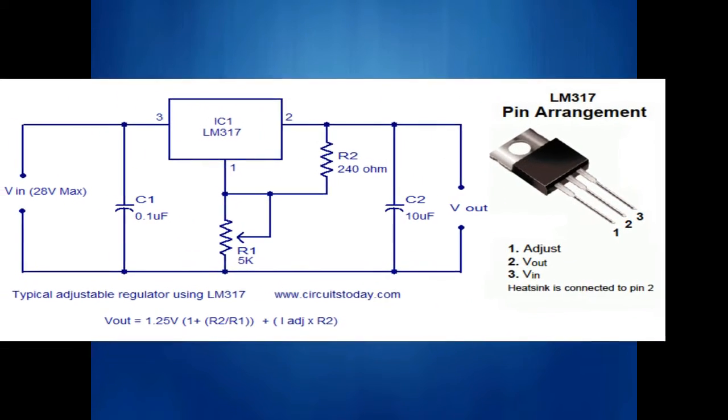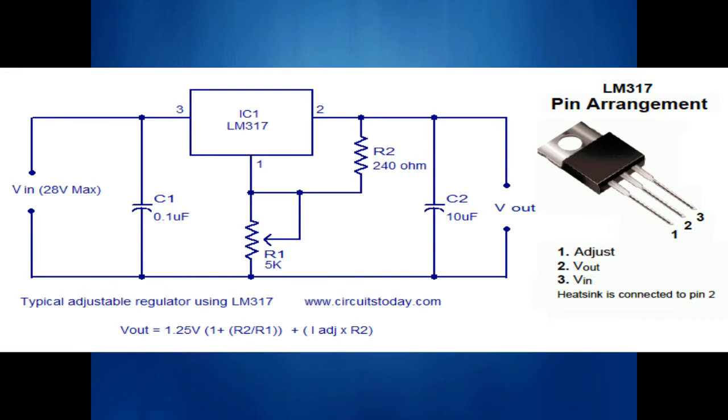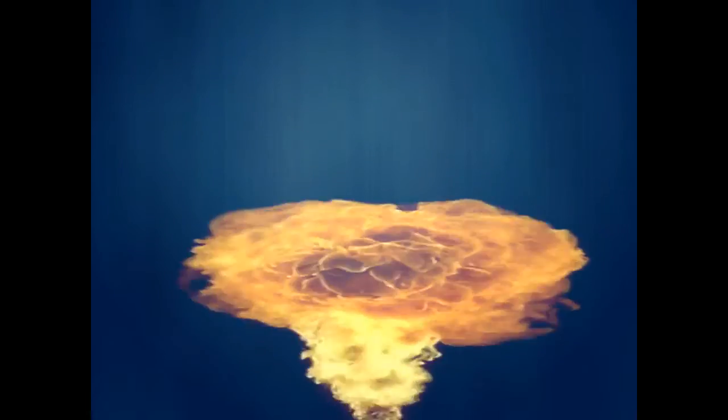Its main function is to maintain a constant DC output voltage. However, it also rejects any AC ripple voltage that is not removed by the filter. The regulator may also include protective features such as short circuit protection, current limiting, thermal shutdown, or overvoltage protection.